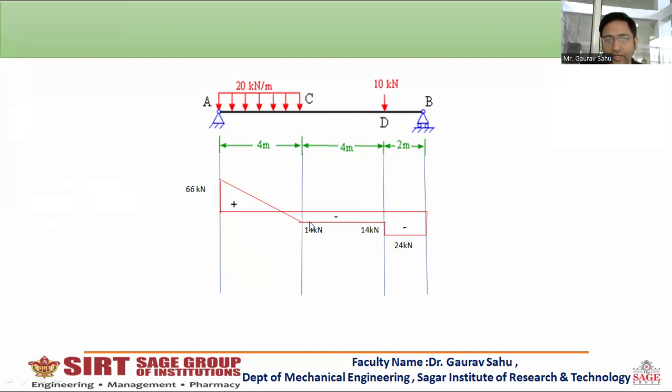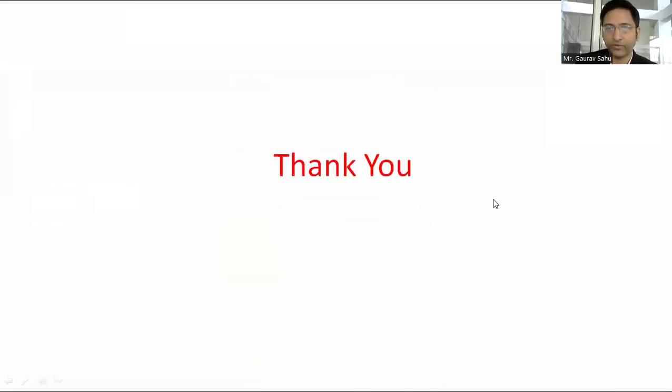You can check over here, and this point where the positive sign goes to a negative sign, we will have a 0. This is known as the zero shear position, which is very significant in calculating the bending moment. So dear students, this was all about how to calculate the shear force value.